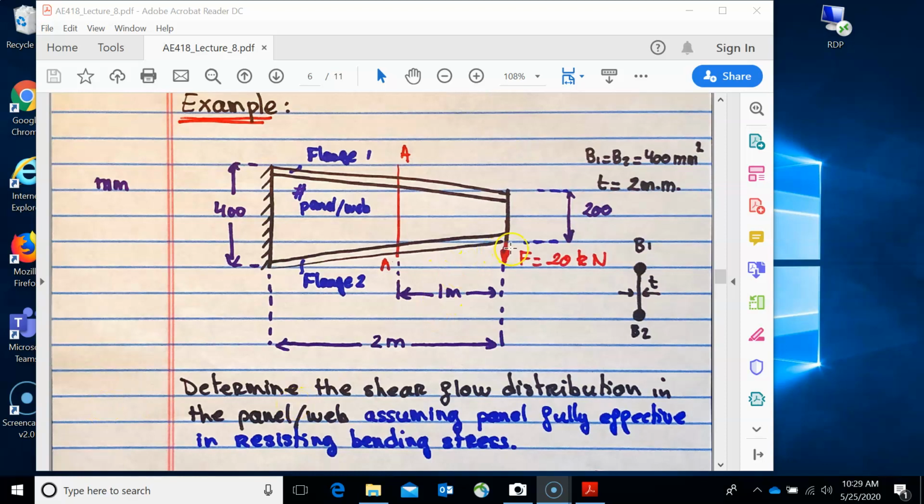Okay, so today we're going to do the final element for this spar web. This is the flanges, this is your cantilever, and this is the web, the panel. In the previous video or lecture, we studied that we have two different cases. The first one is when we assume the panel just carries shear, and option 2 is that this panel can sustain shear, but also some of the bending moment due to this force over here.